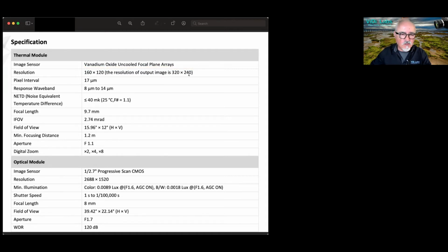A lot of thermal cameras will do that, so that means they do internal upsampling from the 160 by 120 to make a bigger picture, because 160 by 120 is very little. So they upsample it, which we are not going to use for calculation because that's actually artificial, so it's not the genuine native resolution of the sensor. This is achieved in order to make the picture bigger, so often the dual sensor cameras may even have overlaying of the thermal imaging over the visible spectrum.